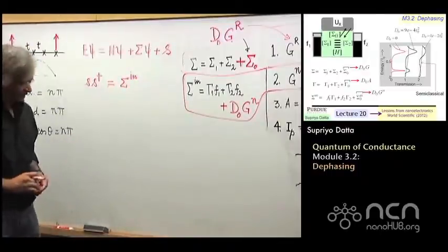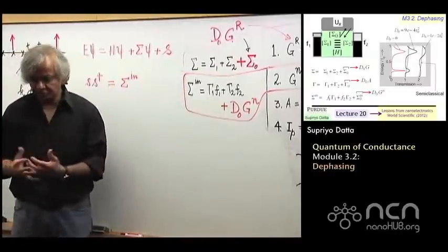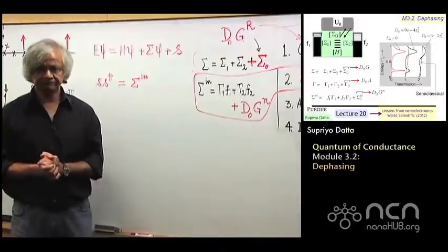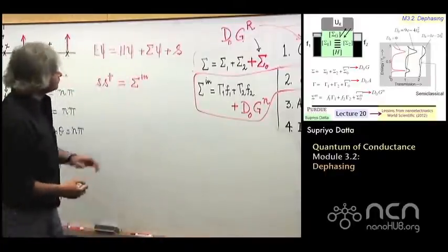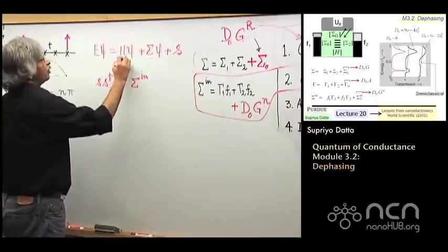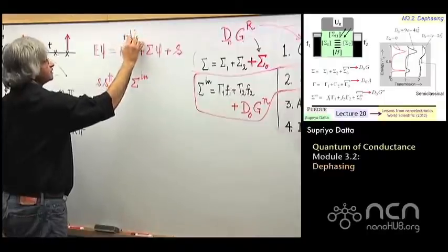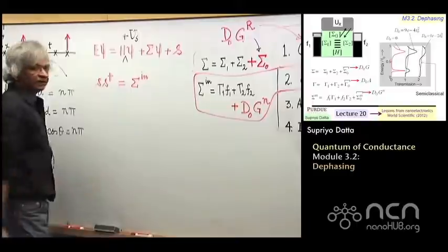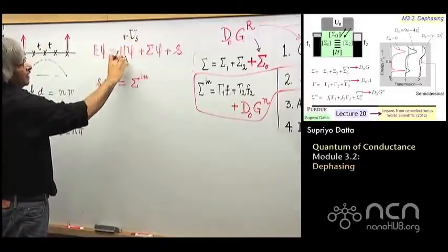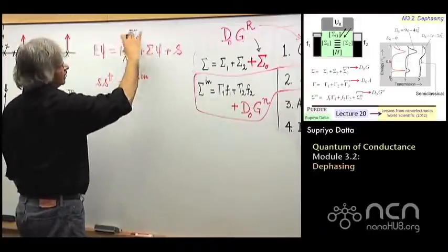Now, supposing there is a scattering potential. What that means is when the electrons are going through the channel, it feels some potential due to the surroundings. Due to the scattering potential, ordinarily you'd put it in here: H plus US, the strength of the scattering potential. But supposing, instead of thinking of it in H, we think of this additional term as another source term.